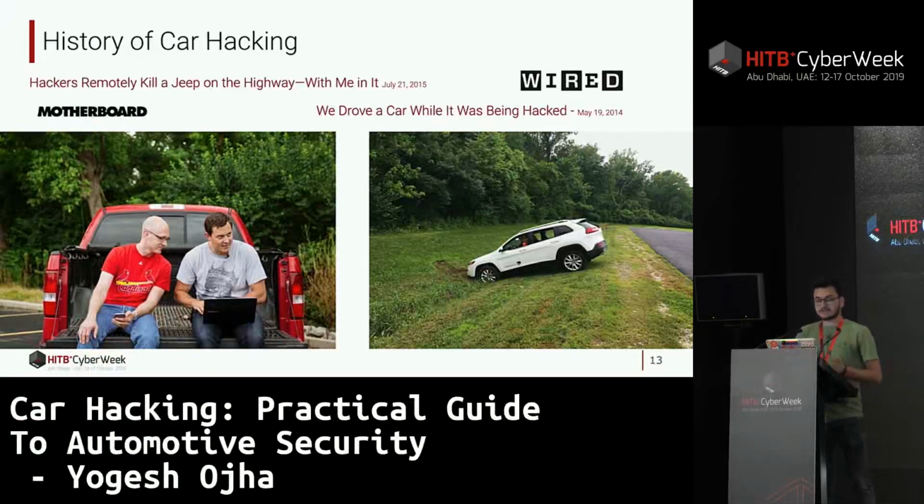They remotely controlled the braking, steering, throttle, and other controls of a 2015 Jeep Cherokee. They demonstrated that it was possible to remotely control the vehicle control unit from a telematics unit that had a cellular network connection. They gained access from the cellular network to the intra-vehicle network through a CAN bus. They then identified that the automotive data packets should be protected with mechanisms like TLS and encryption, but sadly, this was not addressed by any of the car manufacturers.